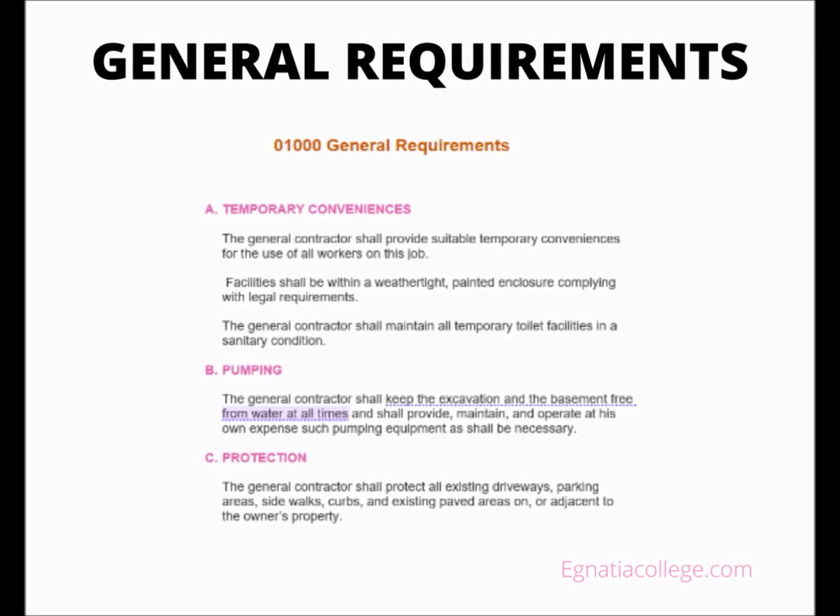The general contractor shall keep the excavation and the basement free from water at all times and shall provide, maintain, and operate at his own expense such pumping equipment as shall be necessary. Protection. The general contractor shall protect all existing driveways, parking areas, sidewalks, curbs, and existing paved areas on or adjacent to the owner's property.